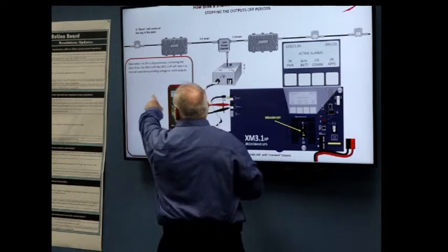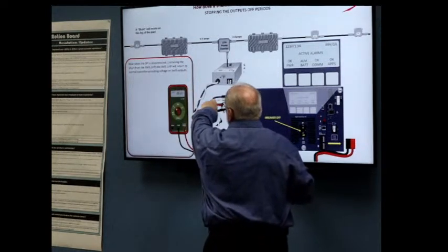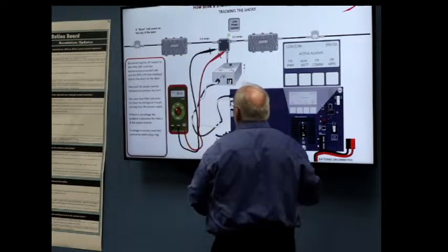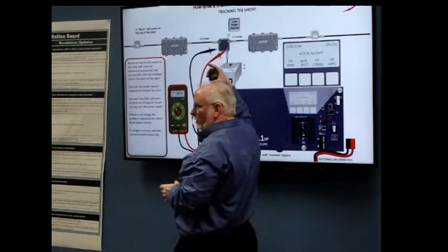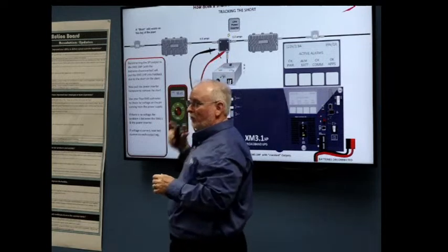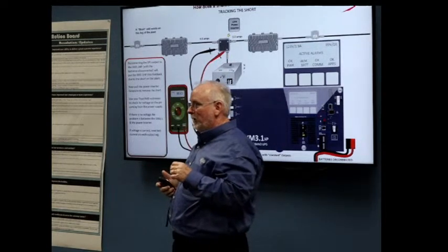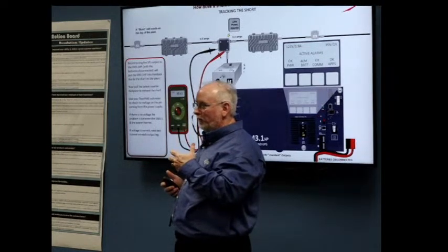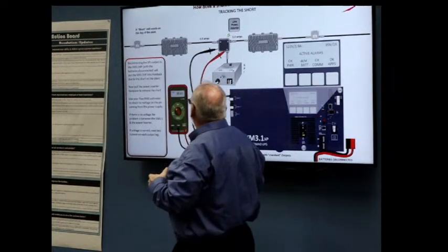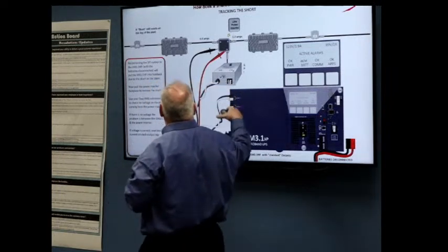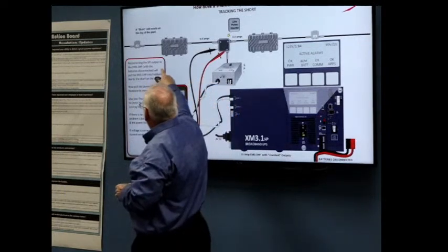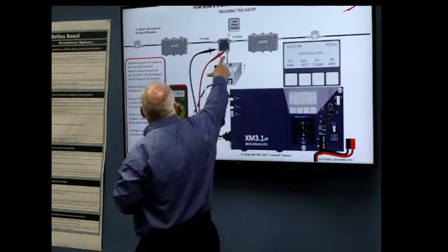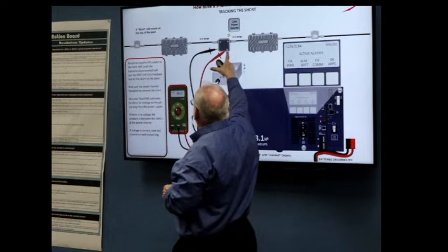Now, when measuring it out, make sure, pull out the SPI, make sure the power supply is working normally. Okay, everything's fine. Then plug it back in, pull the faceplate off the power inserter. Now again, if you're doing this under power, you may get a small arc flash. So wear appropriate protection, right? Or goggles, because you don't know exactly what that is. But if you're working on it hot, go ahead, reconnect the SPI output, power inserter faceplate, using a true RMS meter, check the voltage on the input.